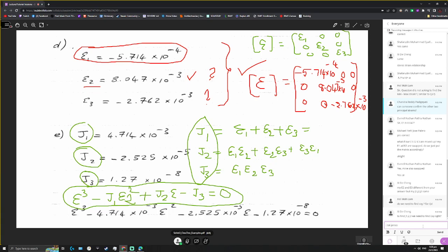So this is the principal strain tensor, and all the other shear strains will be 0. When you are using this principal strain tensor, your J1, J2, J3 will be just like this. If you are not using the principal strains, but if you are using epsilon X, epsilon Y, epsilon Z, then the situation is different. When you use the strains in three dimensions, the calculations will be different. Is that clear, Dixon, Eva?